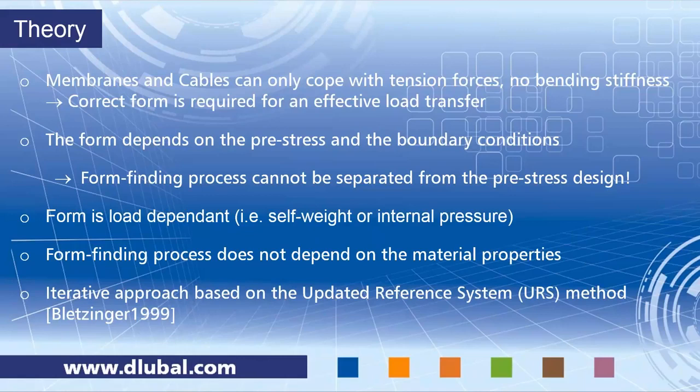So following from this, the form is obviously also load dependent. For example, you can consider the self-weight for the form finding process, or you can have some pneumatic pressure which can be used to pre-stress the structure in practice.